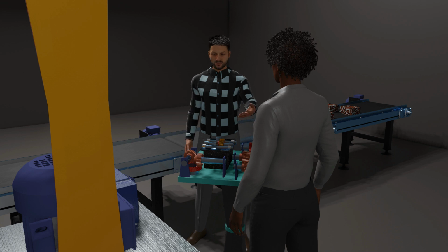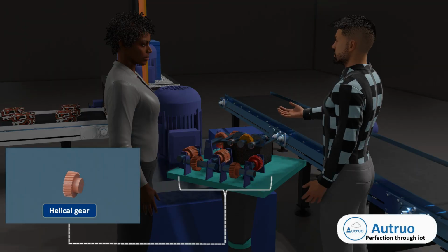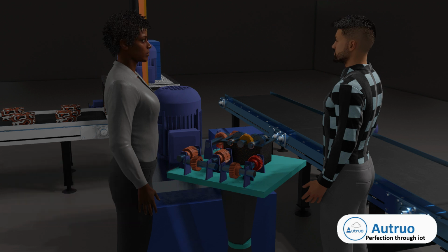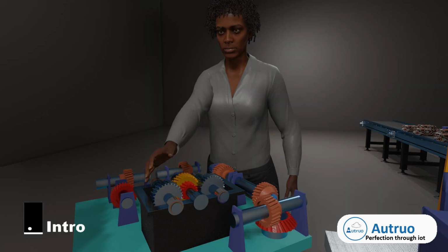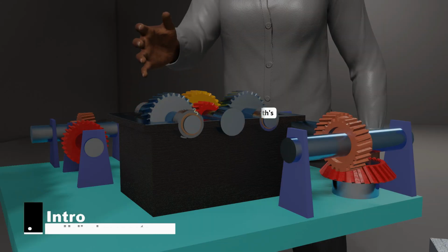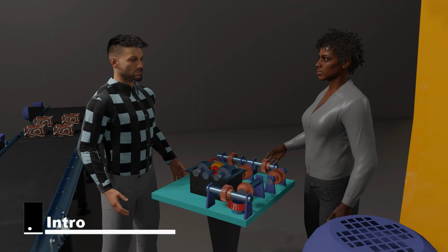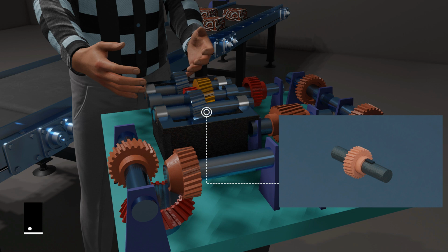Just like spur gears, helical gears come in cylindrical forms in which the teeth follow the pitch surface in a helical manner, but the teeth are not parallel to the axis of rotation. In a nutshell, helical gears are gears whose teeth are angled. The helix angle varies, but it is typically between 15 and 45 degrees. Based on this design, more teeth will be in contact during the gear set operations. These gears will be further connected to the shaft via the appropriate keyways.